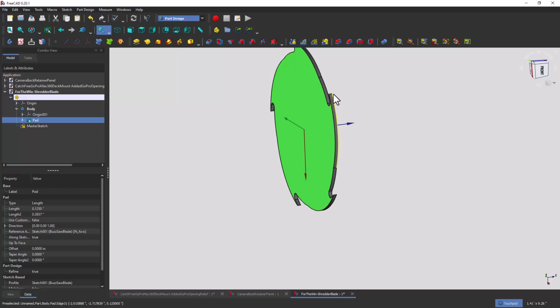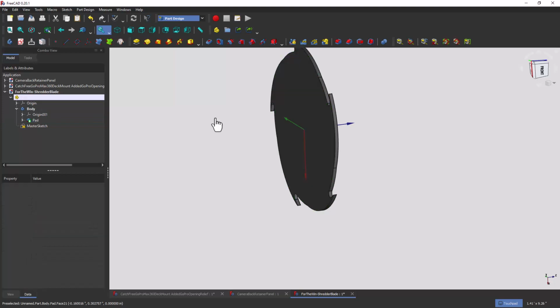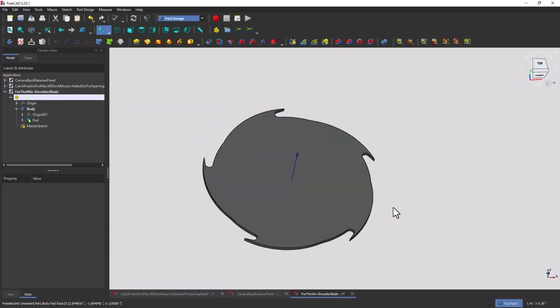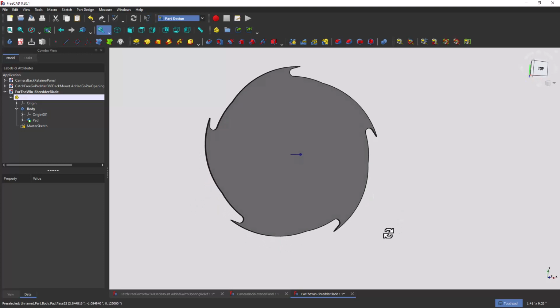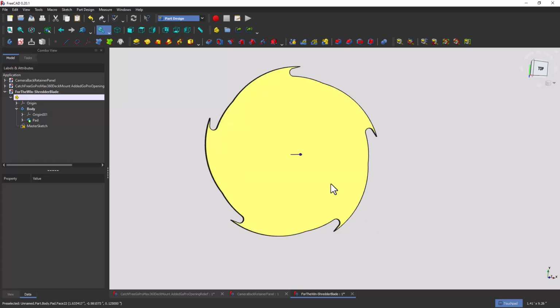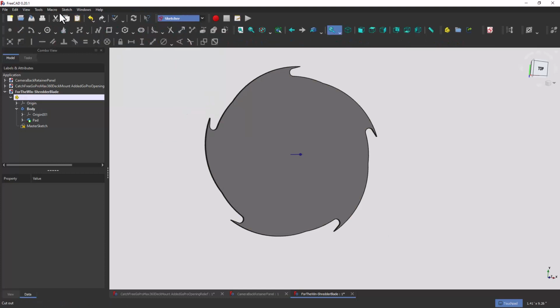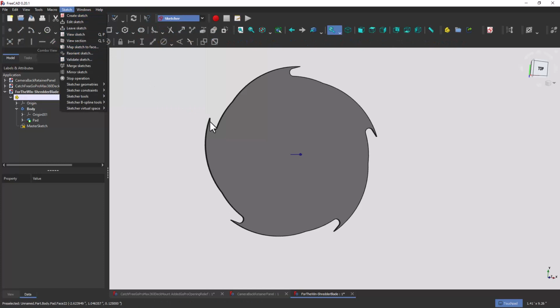However you want to make the sharp point on here. Anyway, so that's all done. Hopefully that helped. A little bit long-winded, but I had to learn something in here as well. When you do a lot of this editing and deletion of all this web of superfluous, redundant lines in the sketch, you're going to end up with problems, and your friend is going to be running over to the sketcher and going under the sketch, validate sketch area. Okay, so that will take care of that.